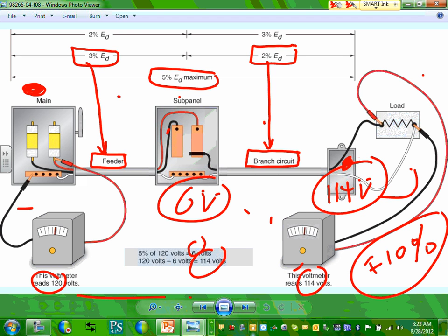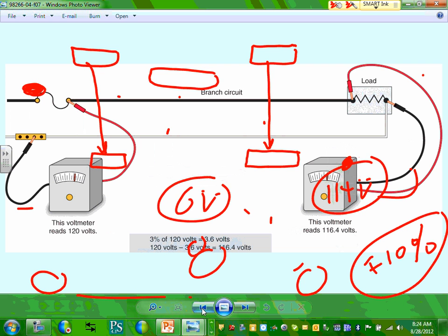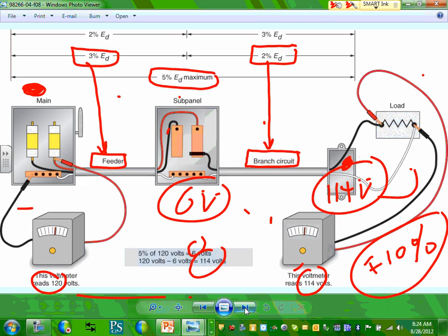Now, if you guarantee that you're not going to go less than 5%, then you're well within the parameters of the equipment. Cool. Everybody knows why we care about voltage drop, because you want the voltage here to be 120 and the voltage right at the terminal of this light to also be 120. So that's your voltage drop on the branch circuits and feeders.